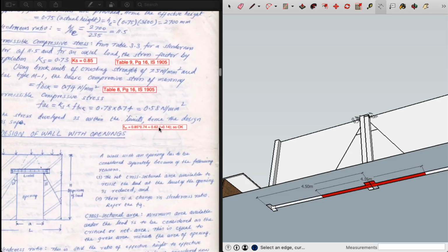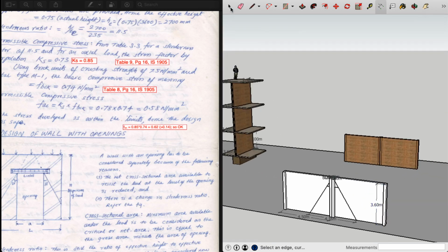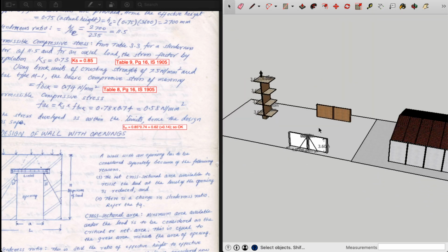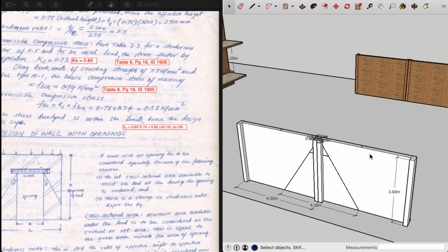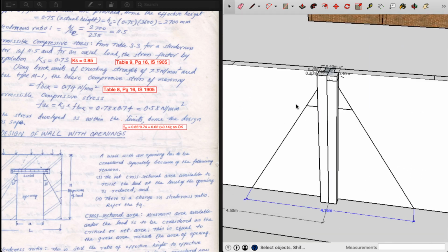Now, the permissible stress that can be allowed in that area is 0.62, and 0.14 is well below 0.62, which is safe, so we can consider everything to be in a safe range in terms of load. This is how you solve when it comes to concentrated loads. It's similar to UDLs, but for concentrated loads you need to find the span of load application through the trigonometrical approach where the load is dispersed at 30-degree dispersion.